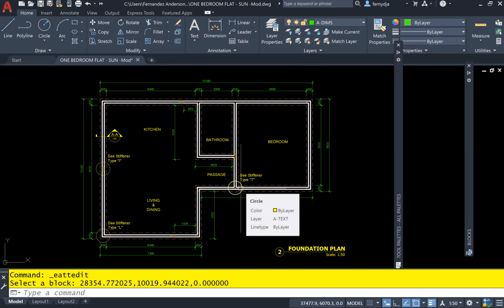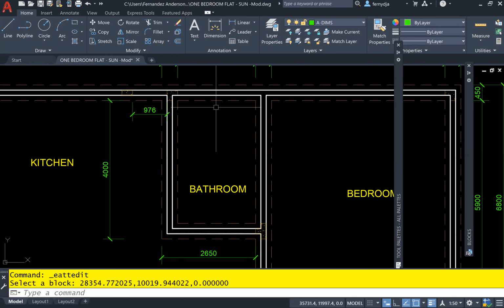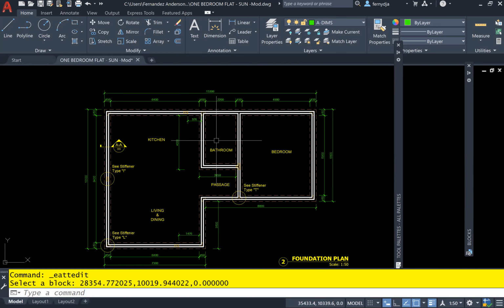First, you would turn your lines into polylines. Remember, when you're doing the foundation plan, we do not include those non-load bearing walls. In our case, there were two walls. We have the linen closet and the closet wall. So what we did was to make a copy of the walls from our floor plan before we included any openings and any other non-load bearing wall.